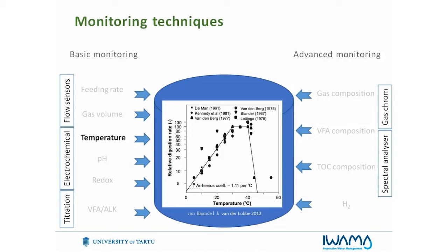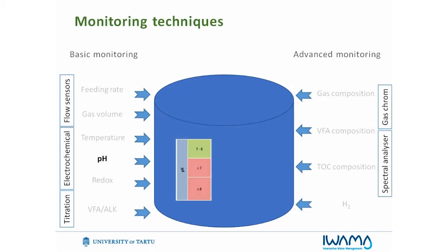Biogas production and biogas composition give us information about the stages of the anaerobic digester. Temperature range: a mesophilic digester is around 35 to 37 degrees, and that gives us a quite stable process. However, the most important is to have a stable operation in the same range, not fluctuating too much. Changes are always bad.